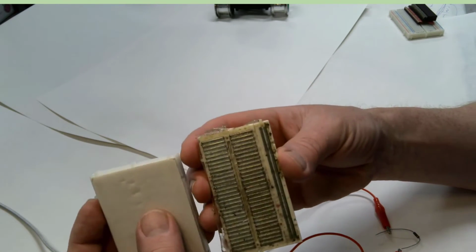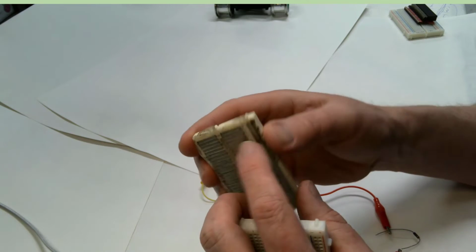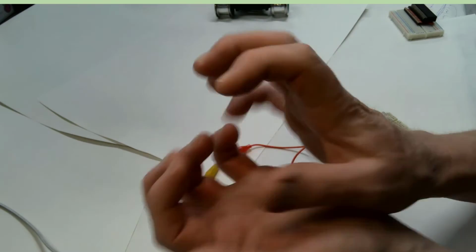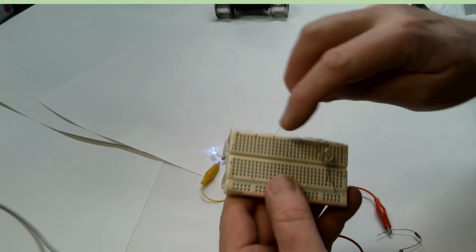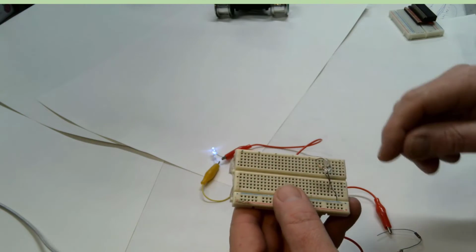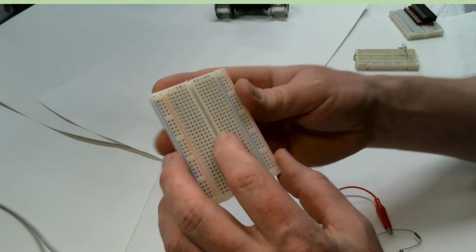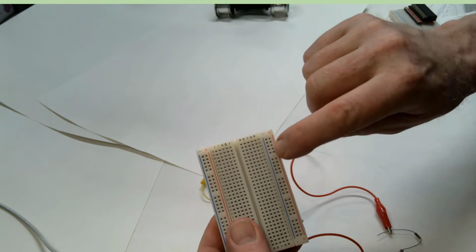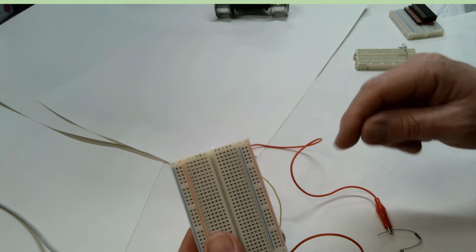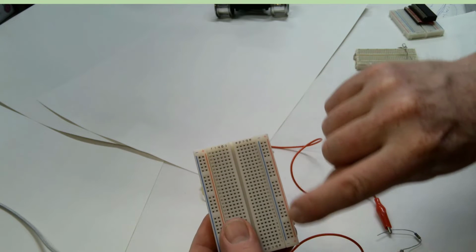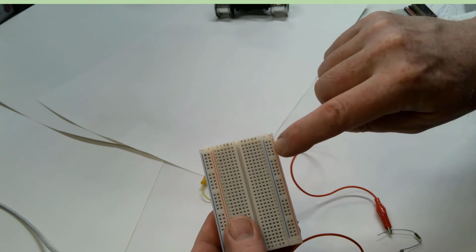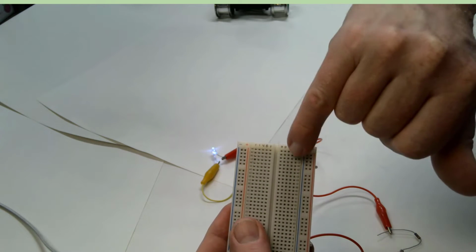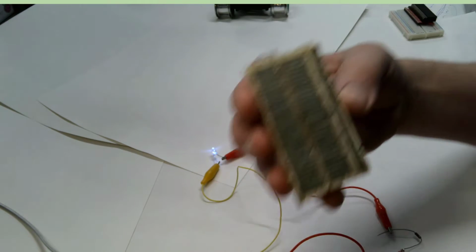So beneath the breadboard are these little metal strips, and the metal strips have these little finger-like pieces that come up and they grab anything that sticks into these holes. And the holes are electrically connected together, going side to side and going along the sides here. So if I plug in 2 wires to the same set of holes along this edge, they're electrically connected together. And if I plug in any 2 things across here, they're electrically connected together, but not as they go from side to side. So again, take a look here.